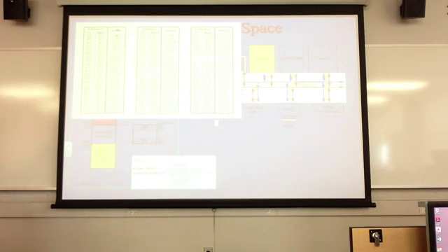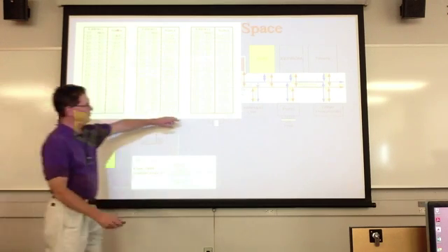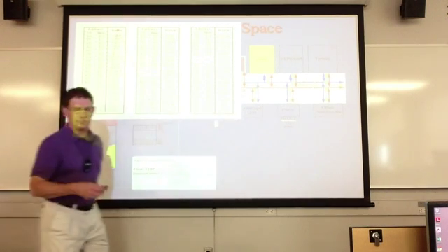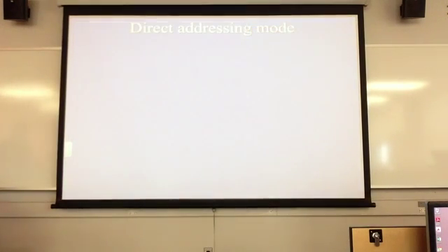All right, so all this stuff in here. Here you've got a timer counter. You don't have access to port A and the others; I think it goes A through F. You only have direct access to ports B and D on your Butterfly board. On the other boards, you have access to them. And if you notice on that slide, the 5E is duplicated there. The status register is physically at 5F, so just note that.